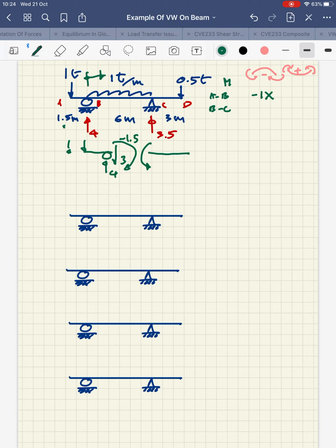So moving to the right, I now have the free body diagram with the negative moment with the same amount and the upward shear equal to 3. So my moment at BC, beginning from B, would be equal to minus 1.5 plus 3x, and then again the term from the uniform load, which I forgot yesterday, minus x squared over 2.